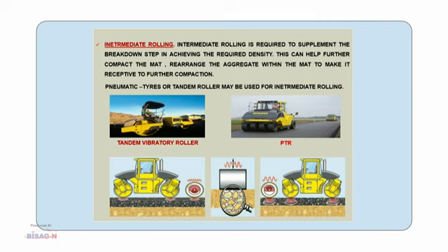We can see in this video that while doing the rolling, there is an impression. There is some type of loading in the vibratory mode and static mode, so some impression will be there in the pavement. We can see in this photo the amplitude, and high frequency and low frequency. This is the basic effect while doing the compaction of the pavement.